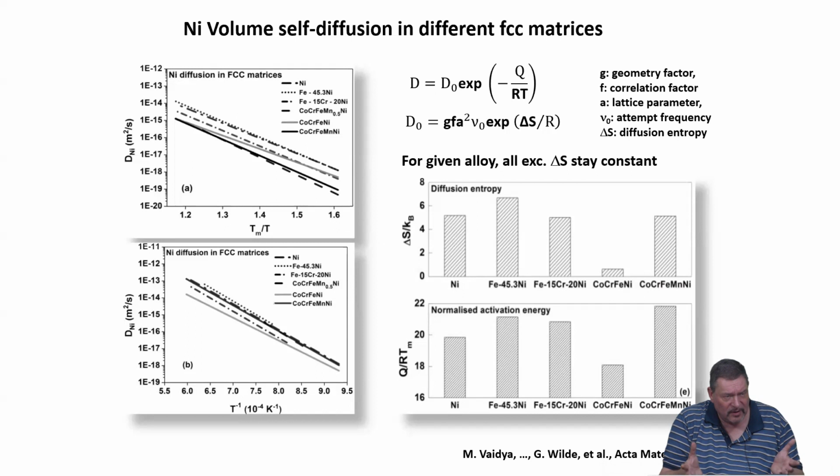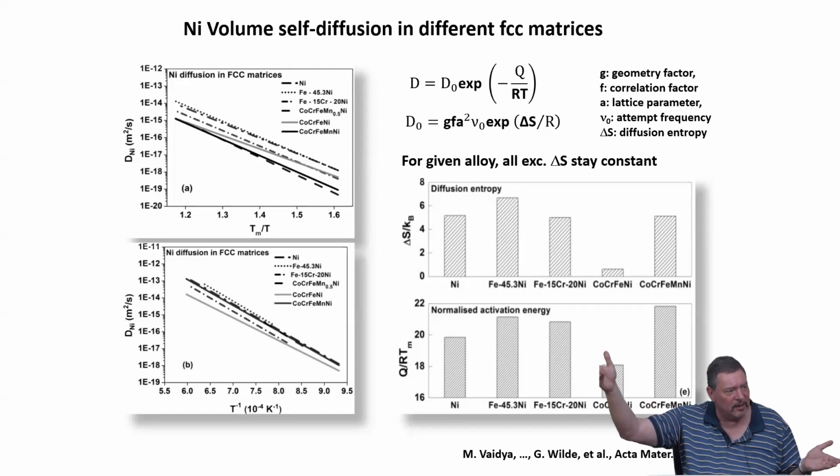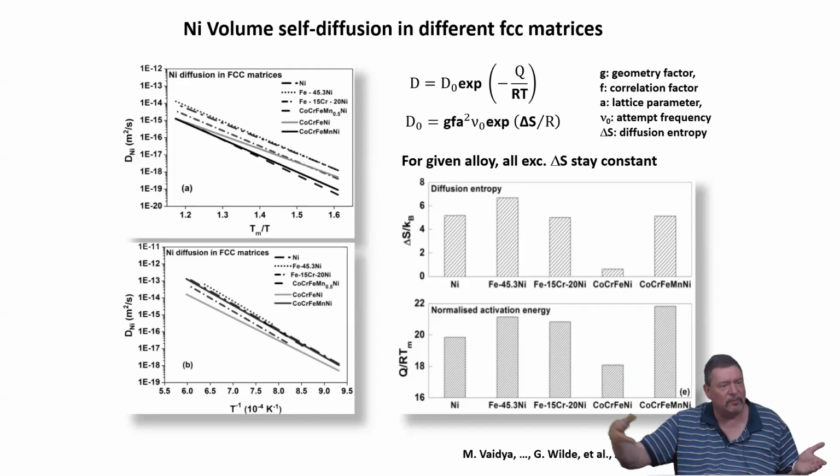They don't necessarily affect the total volume, and as we will later see, grain boundary diffusion coefficients, but they affect storage capacity and retention of high defect densities up to higher temperatures in a non-diffusive way. And this might explain why yield strength is kept at high levels up to higher temperatures. Grain sizes stay stable up to higher temperatures.